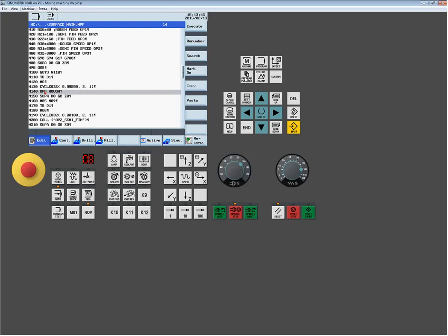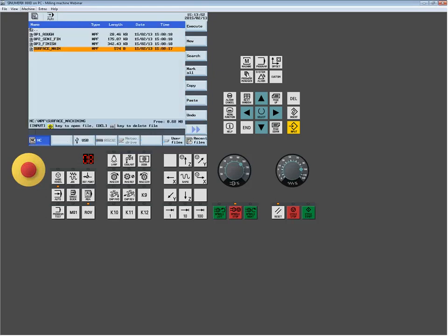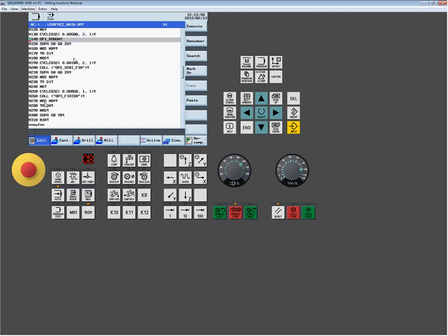And then this right here is how I physically call up my subprogram. The system is smart enough that if you simply give it the name of the file, so op1_rough, as you see it here, you don't need any extensions, nothing. And the system will automatically start looking within its own internal memory. Wherever it finds that program, it'll start to run that program.